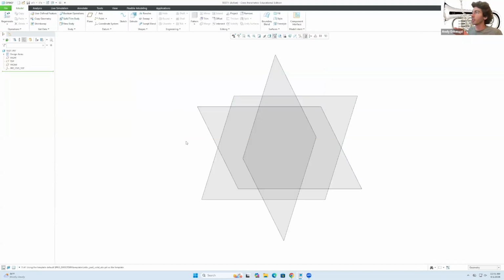A couple of things before we get started: you will see these three planes in here. They denote the 3D space where we'll be, and essentially everything that we'll draw from now onwards, parts, 3D models that come out of this, will be defined with respect to these three planes, or to be more precise, the intersection of all of them, which denotes the origin. It doesn't matter where I draw something, as long as there's some reference with respect to the origin, the software will know where that part is in place. So it's super important that you always have that idea in mind. And I'm going to re-emphasize that in just a little bit.